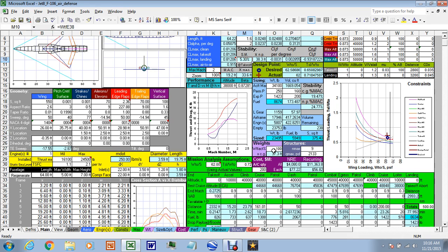When it goes supersonic, it'll have 30% static margin, something like that. So that's a reasonable balance for this era. We'd go unstable with a more modern airplane, but we're talking about an airplane designed in the 50s. So let's just optimize it there. Alright, what else do we have here?